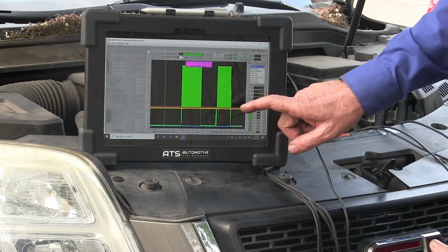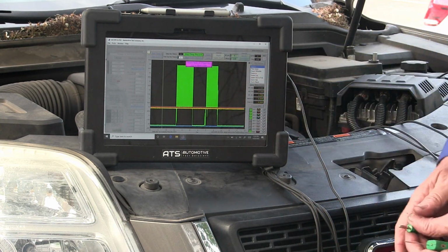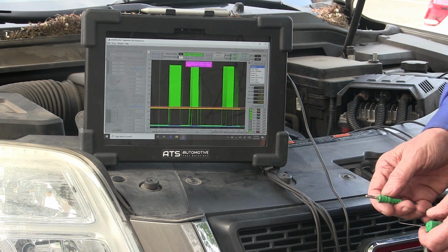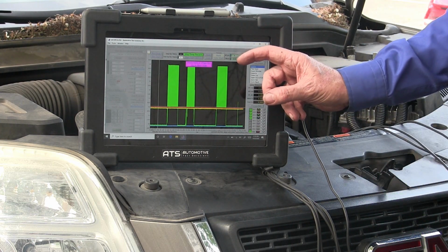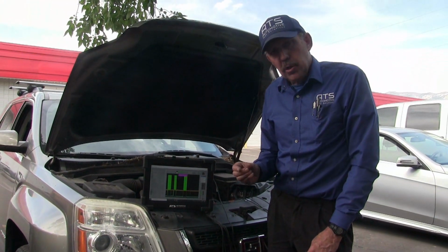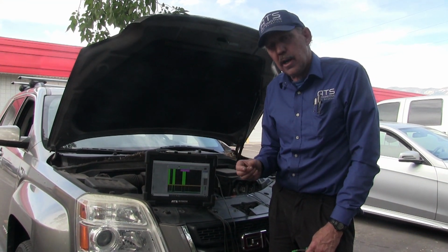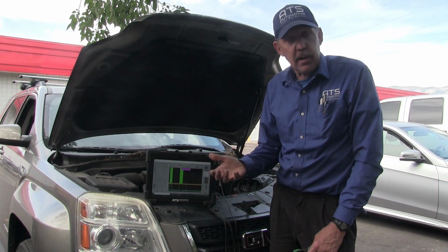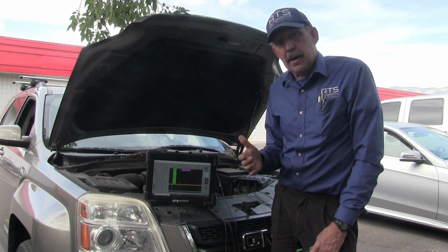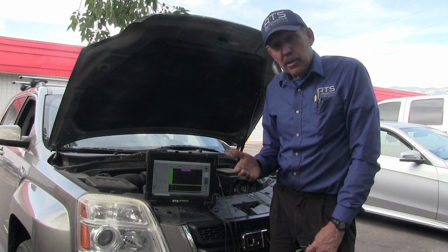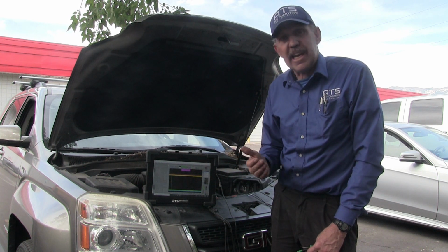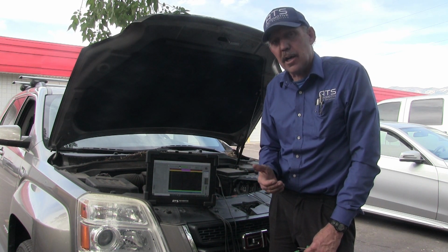Now that frequency, it's important to realize that it's going to 5 volts. So when I connect this to the O2 signal, I should have 5 volts. If the O2 bulb is cold, the O2 has greater than 100 million ohms. It's an open. The other end of this circuit goes either into a MUX, a multiplexer, or into an ADC, an analog to digital converter.